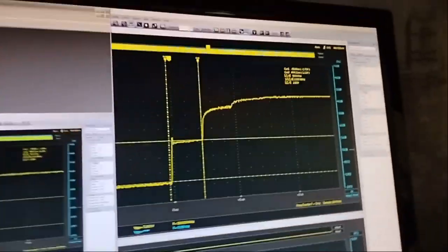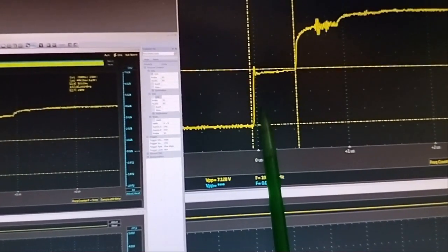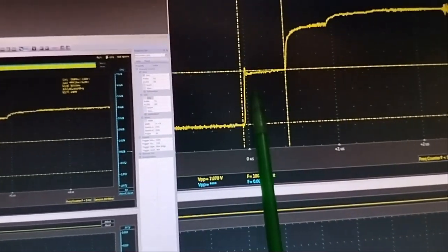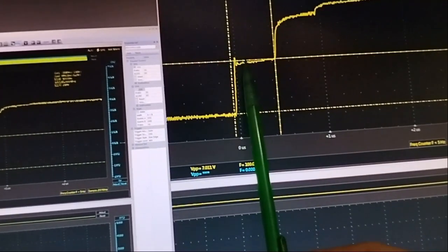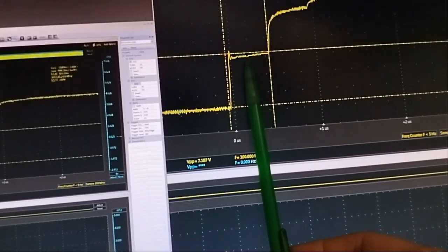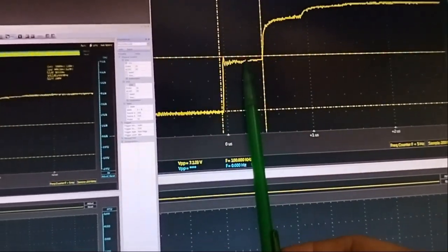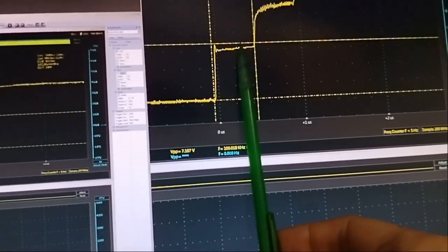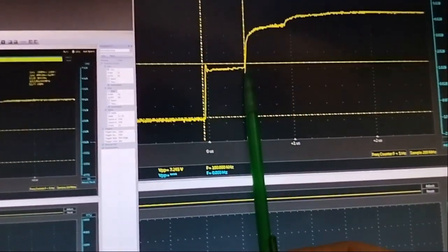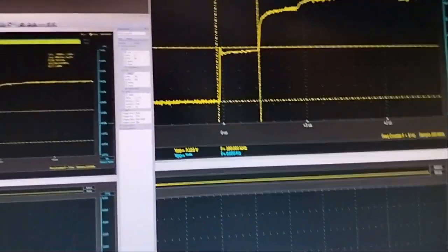And here is the graph. Now I don't have the blue line, I have just the yellow line. This is the moment when the pulse is coming to the cable. This point is where the pulse is reaching the end of the cable, and then it is reflected from the end and travels back to the initial position, the beginning of the cable, and then we have a spike again. So at this moment I'm going to move this potentiometer.